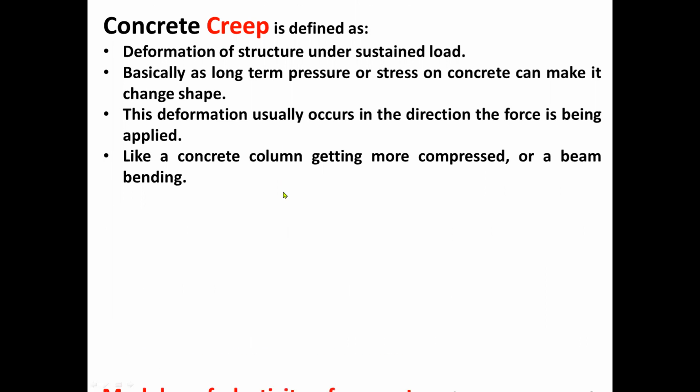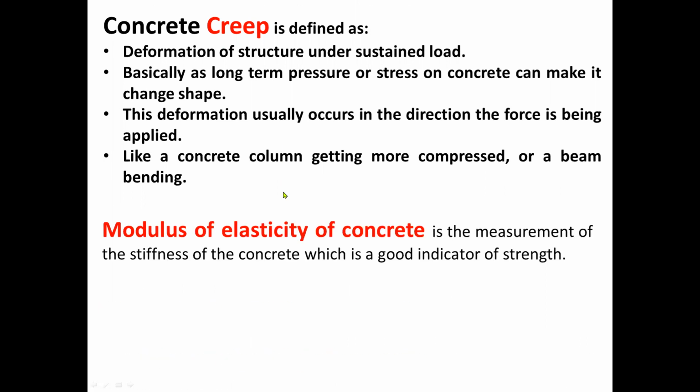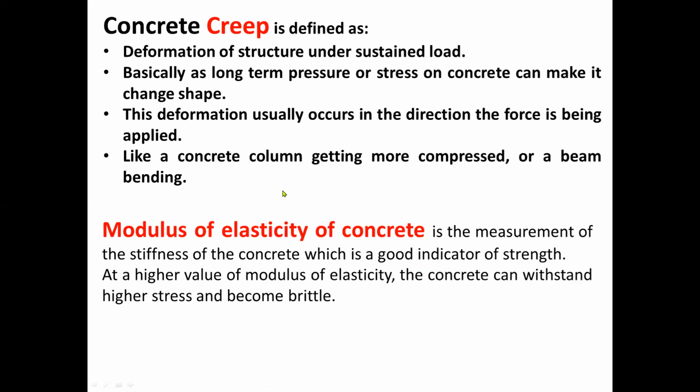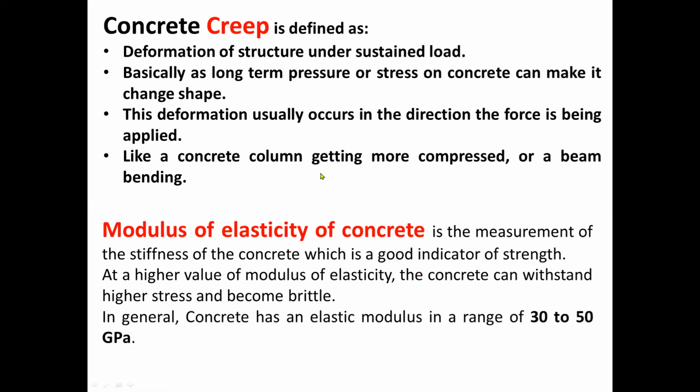a beam bending. The modulus of elasticity of concrete is actually the measurement of the stiffness of the concrete, which is actually a good indicator of strength. At a higher value of modulus of elasticity, the concrete can withstand high stress but becomes brittle. In general, concrete has an elastic modulus in a range of 30 to 50 gigapascal.